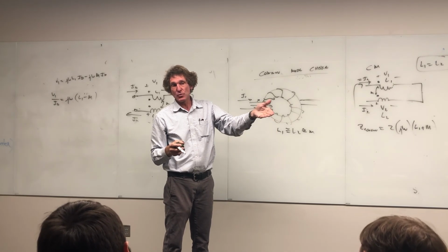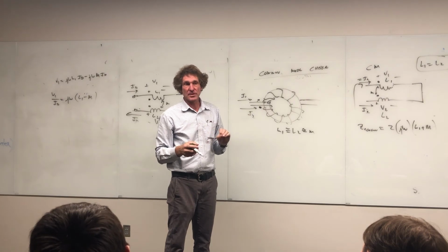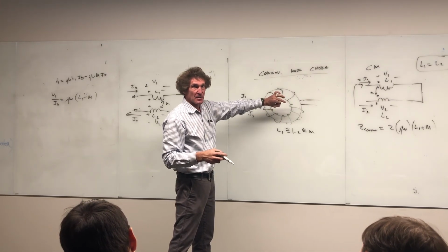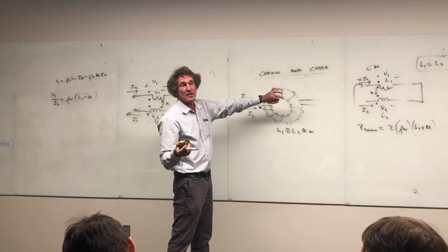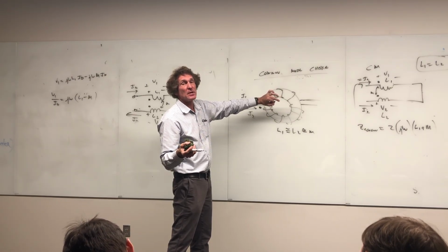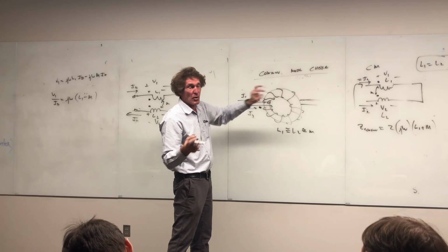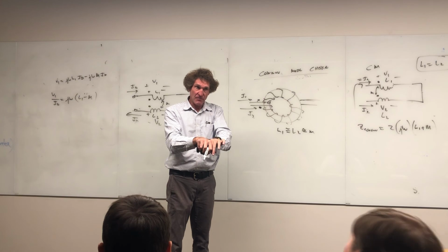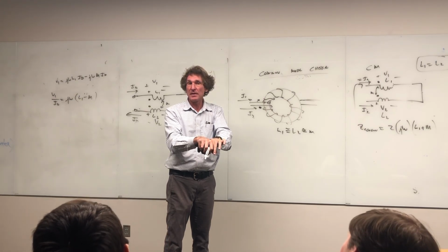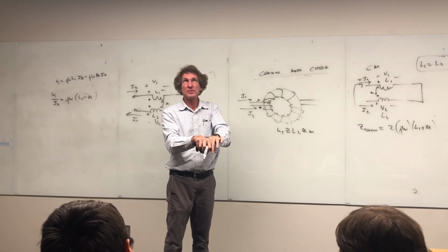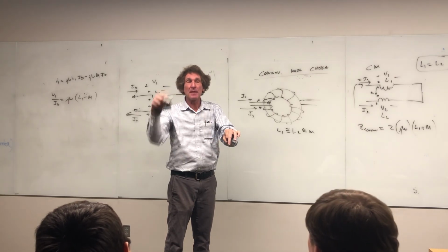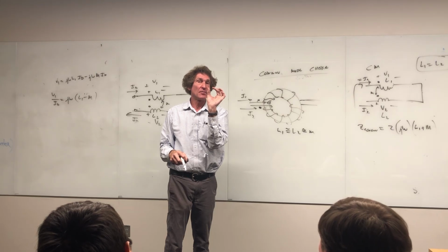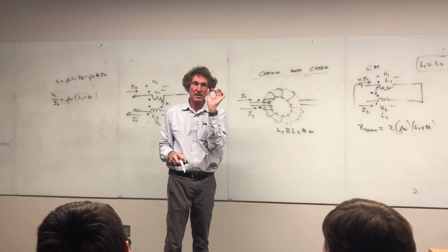So what you need to do when you do these things for lightning protection work, you have to have insulation on those wires that will really be something where, if you wanted something against, say, 1,000,000 volts, you take 1,000,000 volts divided by the number of turns, and that has to be the breakdown potential of two wires next to each other where the insulation's touching.